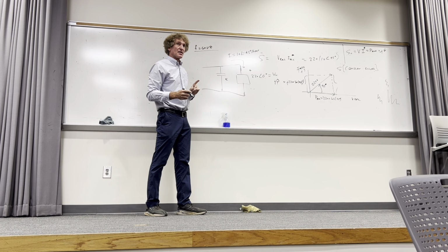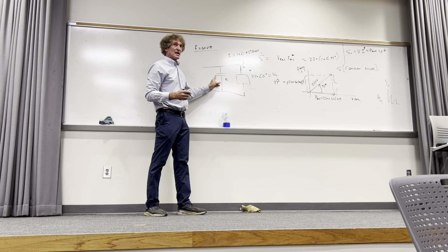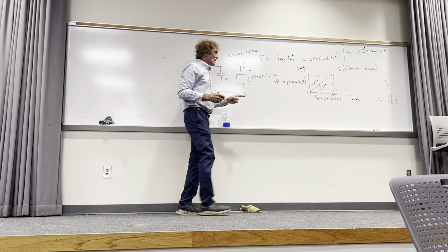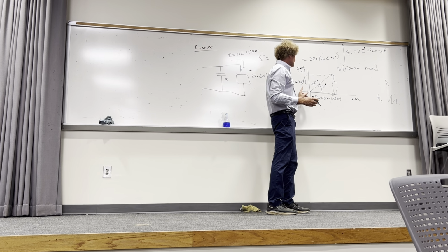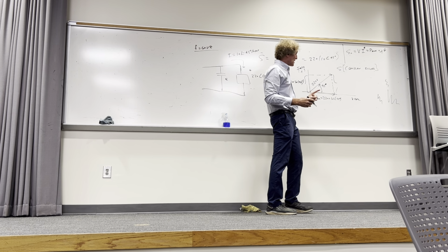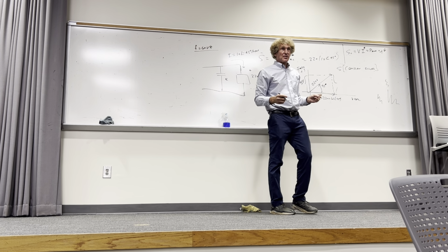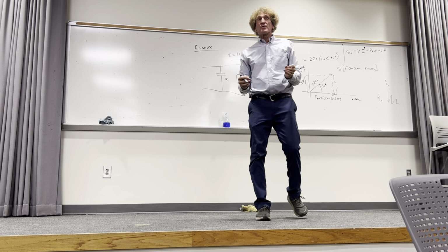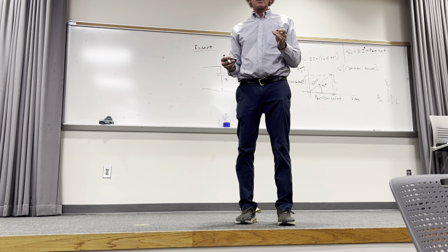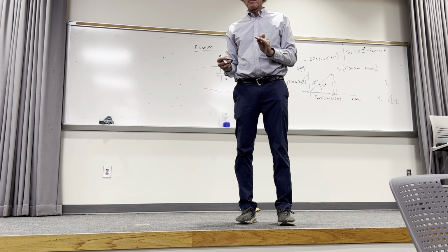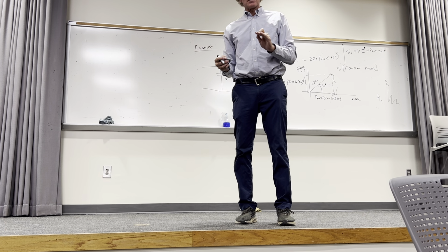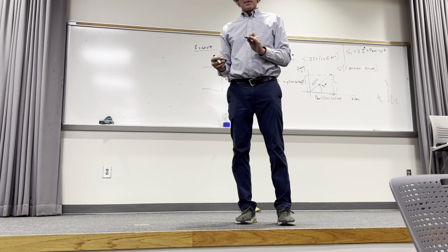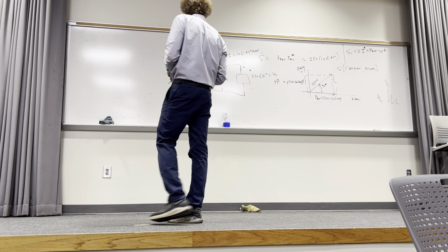Now here's the kicker. The complex power associated with this capacitor, unlike this one that has a positive JQ, will have a negative JQ. So when you add them together, you reduce the amount of complex power. That's the goal. Follow me? We can get rid of it entirely, and I'll show you how. Now make sure you be attentive here.